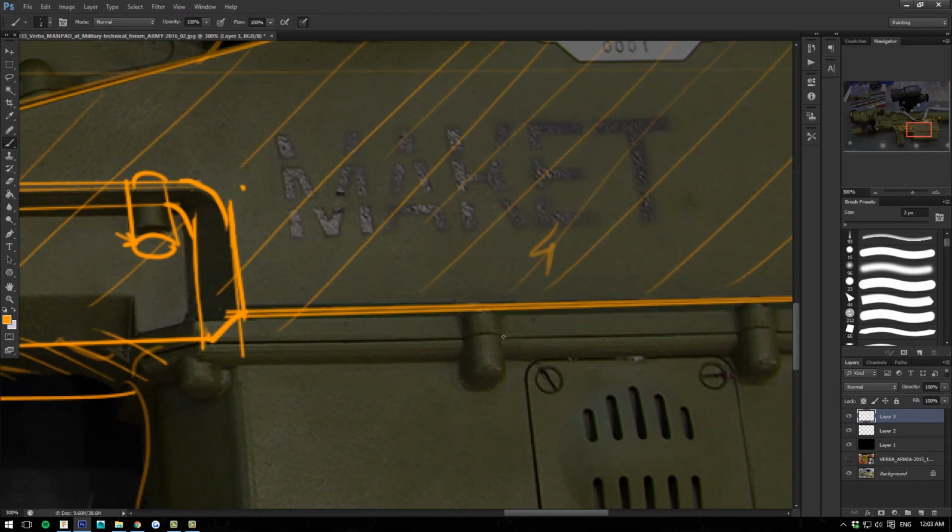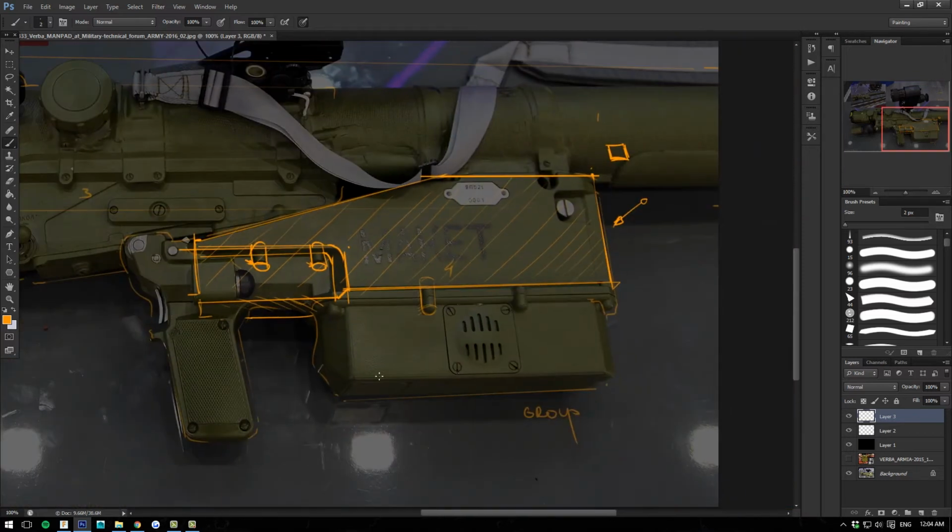And once we insert that cylinder, it's going to penetrate through the geometry. It's going to be rounded on the edge. Once we combine them, we will be able to get this common edge and add a bit of a fillet to help smooth the transition.